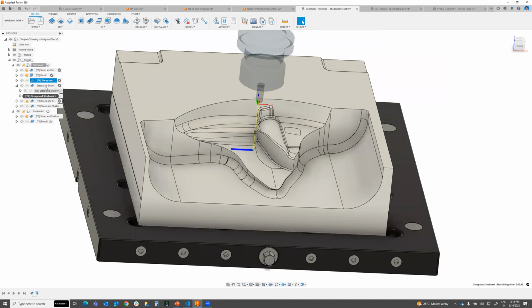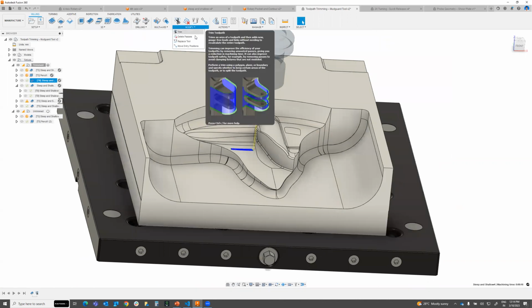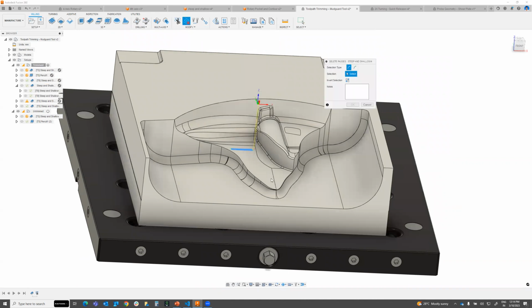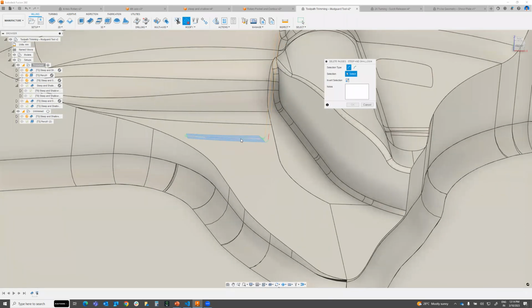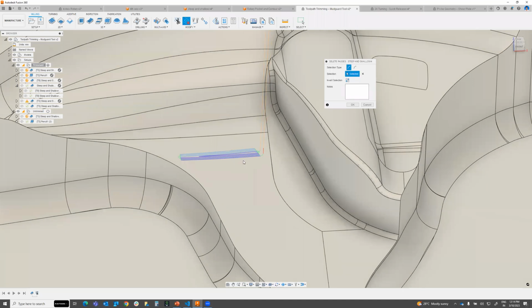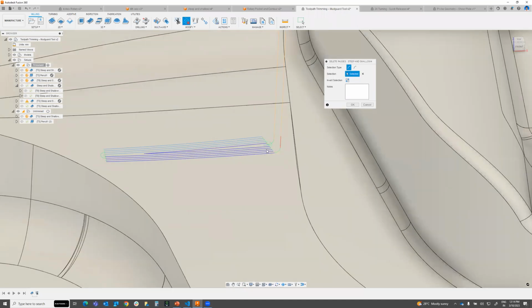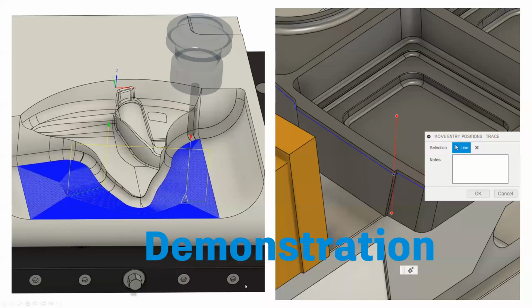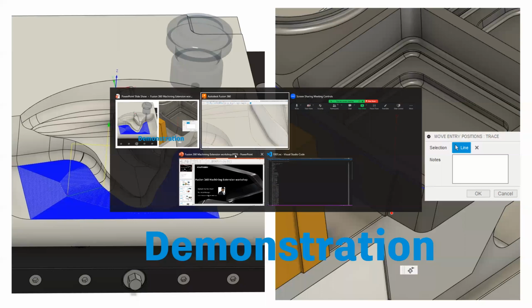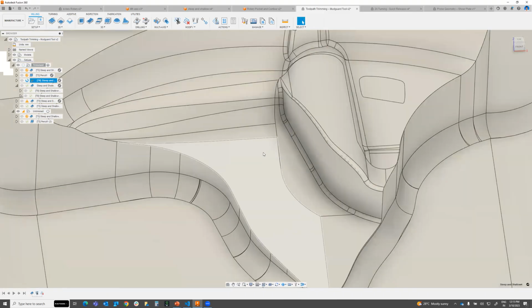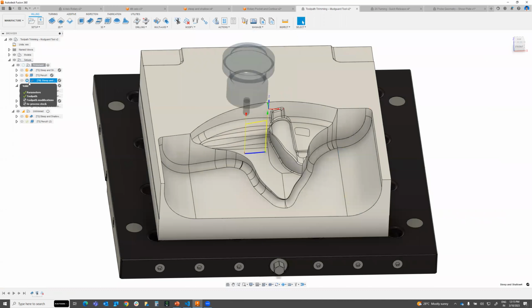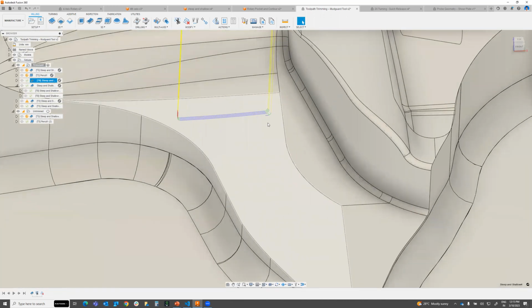Okay. Apart from trimming the toolpath, if you want to delete some passes, it is possible to delete the passes. Suppose you don't require some of the passes here, you simply select them and simply delete them. This is the deleting option as you see in other CAM systems, and it is possible to delete whatever toolpath or the complete toolpath you want, and it will automatically recalculate. Now we can say the delete process was taken and it was recalculated.